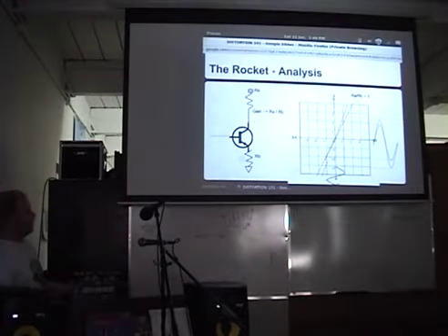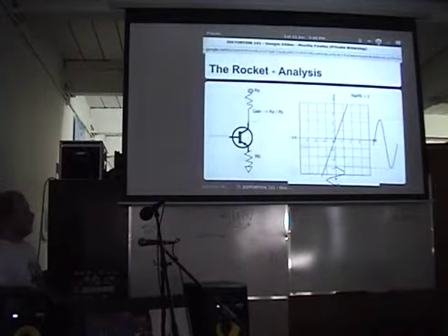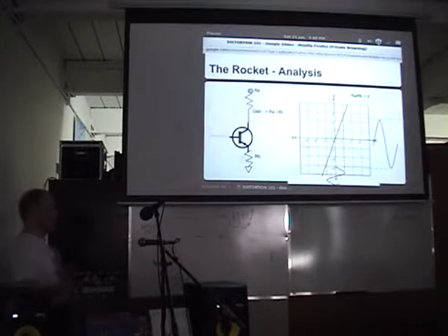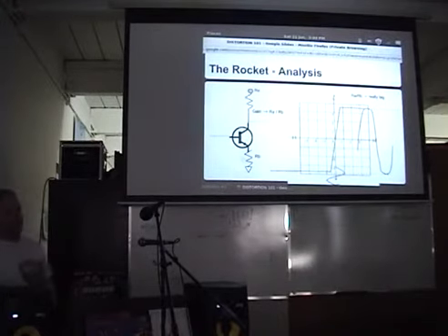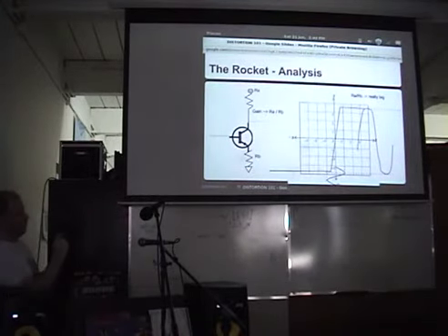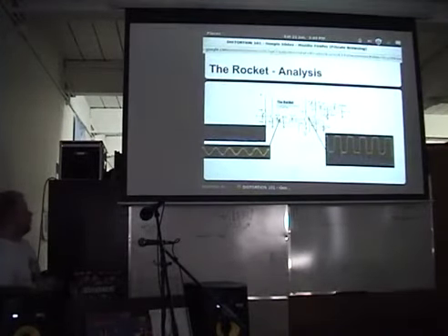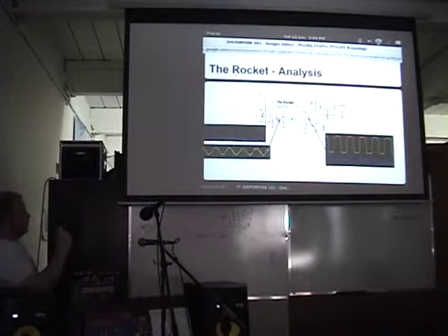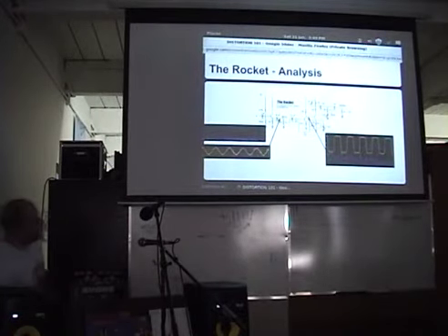If you wanted to make that bigger, you would just change one of the resistors to make this ratio 5, and you get something even bigger. If you want to get interesting and make things clip and sound a little different, you just make that difference really big, and it starts to make things look a little more square and flattened out at the edges. So the same input signal, at the output of our input stage and then measured back at the output of the first transistor, shows this kind of clipping in action.